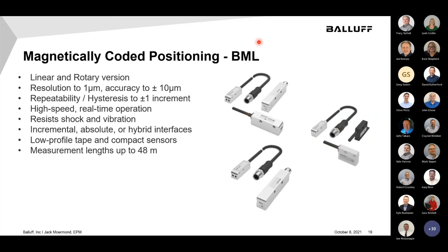A lot of times customers will apply these capacitive sensors in applications where they're looking at water, for instance, and as they heat it, they notice that their sensing distance isn't the same as it was when the water was room temperature. So we need to know what kind of temperatures they're running, because they'll notice that sensing distance change as the temperature increases. So it is affected by it.